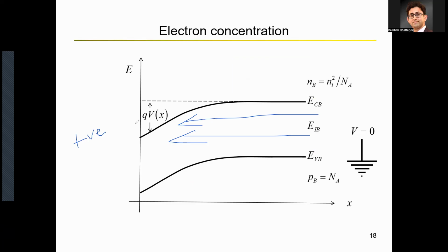Don't try to think about the equations, because equations are what you learn in a device physics class. So you're attracting all these electrons from the right-hand side, and that's why the number of electrons is changing. Since you have a higher number of electrons, you have a higher average amount of energy for the conduction band or valence band on the left-hand side. That's all it means in terms of the graph.